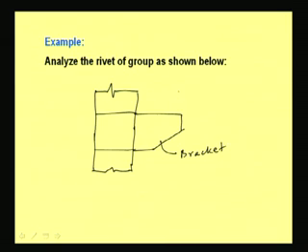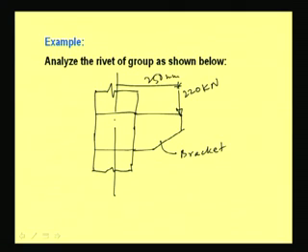Now, the load is 220 kilonewton with some eccentricity of say 250 millimeter. So, eccentricity is 250 millimeter, load is 220 kilonewton, and rivets are given in this way. This is the center CG.